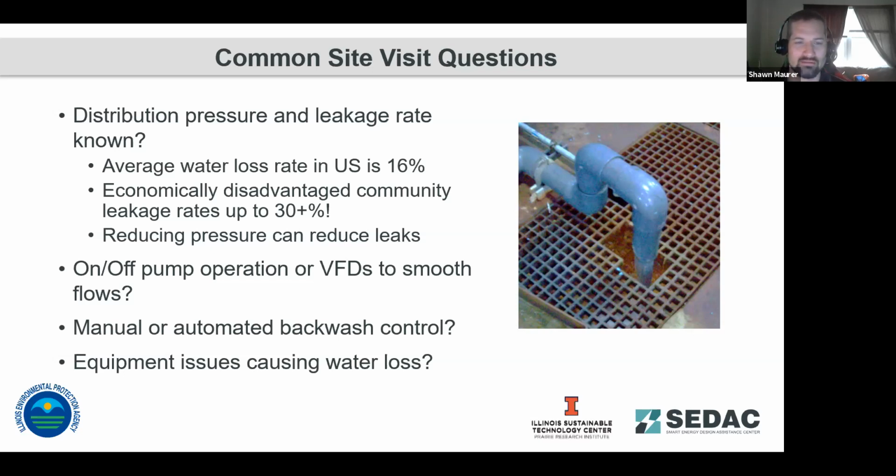We'll also be looking at the operation of pumps and motors on the system. Are they doing some kind of on-off control? Or do you have VFDs to help smooth that flow out? And again, we're looking at a couple of things there. Smoothing out that flow saves energy and reduces wear and tear on those motors.